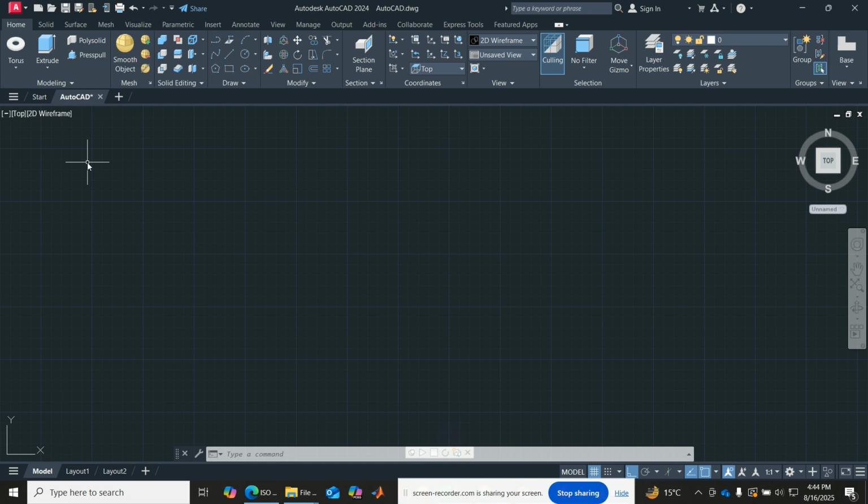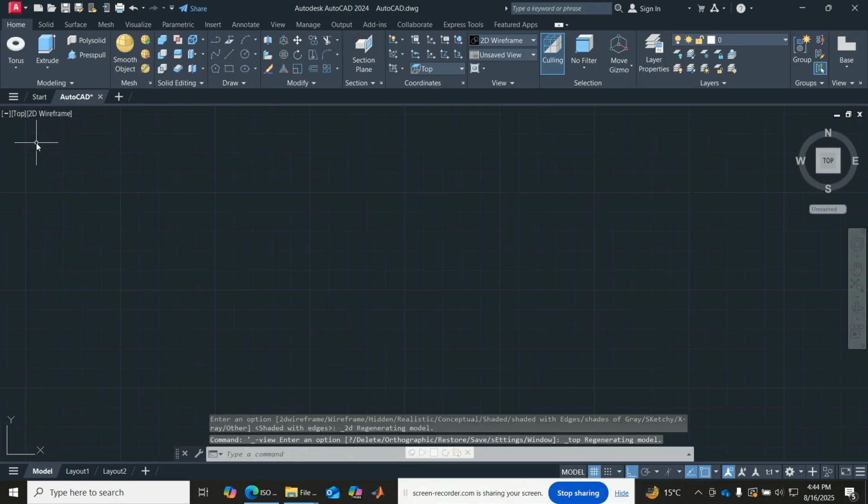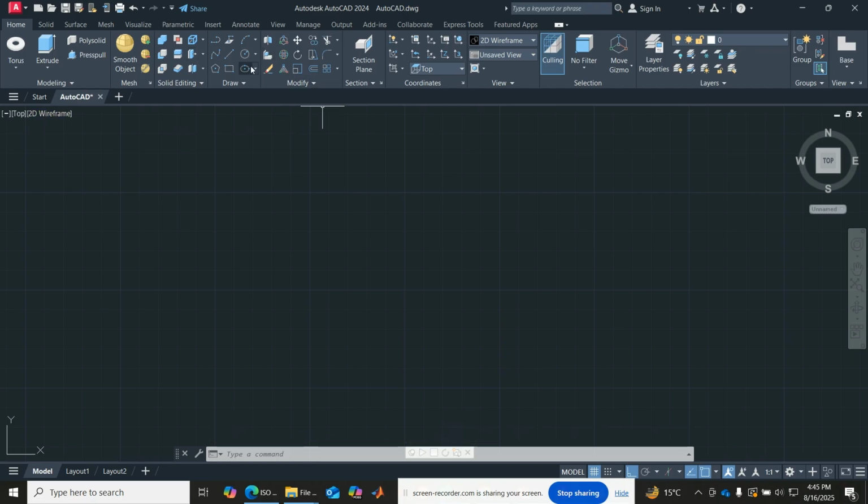So let's say we want to create a rectangular box, let's say from the top, and then I'll show you if we draw the same rectangular box from the front view, and you will see the orientation of the 3D object has changed. So let's say we want to draw a rectangular box from the top. So I've selected here top view. When I want to extrude it now is when I'll take it to an isometric view. So top view, so here this is our drawing command.